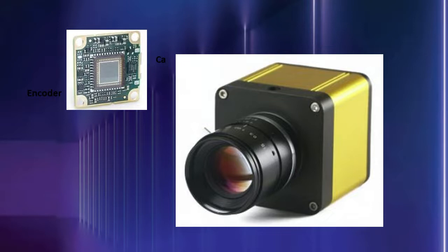For machine vision cameras, this means delivering raw video, with features such as variable scan, trigger, shutter, and more. The typical resolution is 2 megapixels from an array of approximately 1600 by 1200 pixels. The scan rate harkens back to the pre-digital video standards with 33 milliseconds, 30 frames a second, as standard, with other scan rates user configurable. For these cameras, C-mount or CS mount lenses are standard.